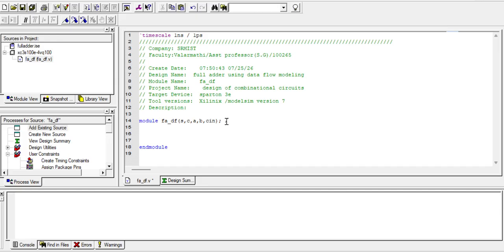Each and every line, at the beginning, you should have a practice of giving the comments for each module. Then you will get a clear understanding whenever you open the file, and you can understand what you have done. So here, this is the port list declaration, the black box. What are the I/O ports there? Specify the ports, whether input ports or output ports. Only specify the I/O ports, not wires.